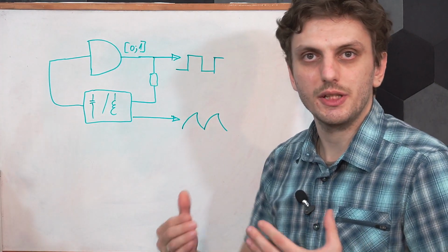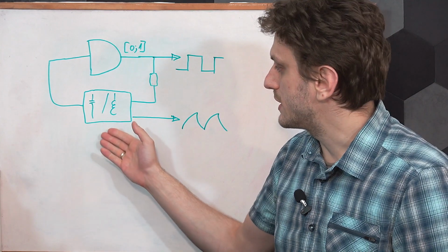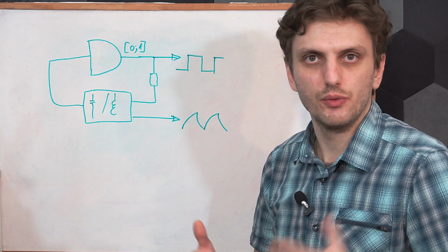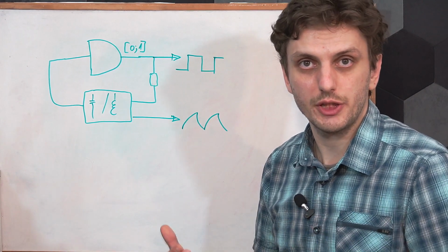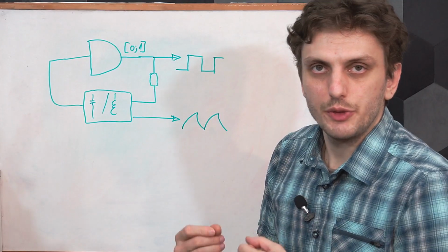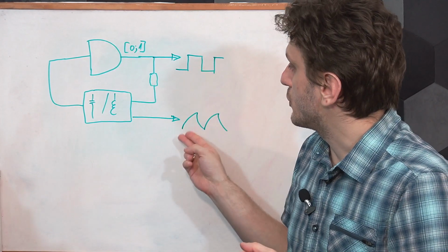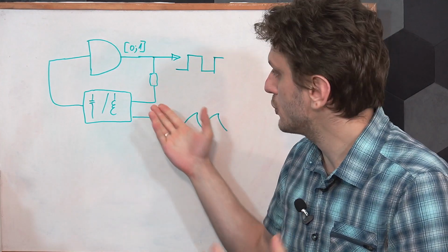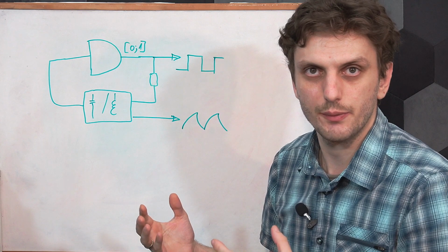So usually the charging and discharging profile of this element will look like a triangle wave. Now, we can use both capacitors or inductors as storage elements, but most commonly a capacitor is used. The way in which you go from your square wave to your triangle wave is by adding a current limiting element. Usually this is a fixed value resistor.